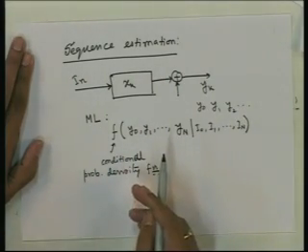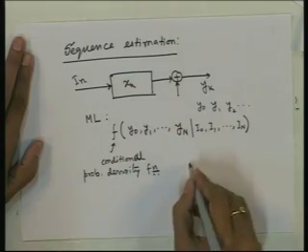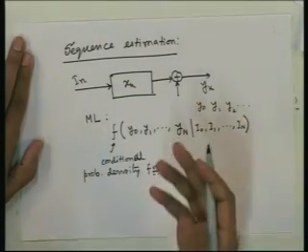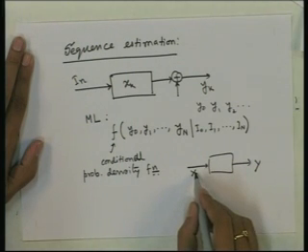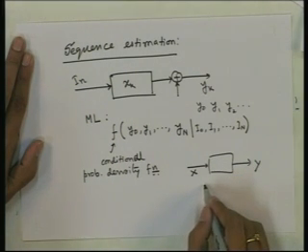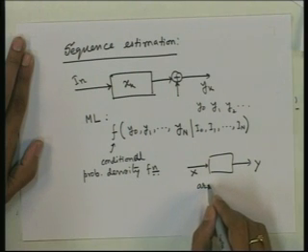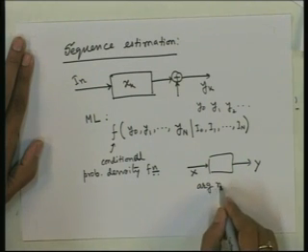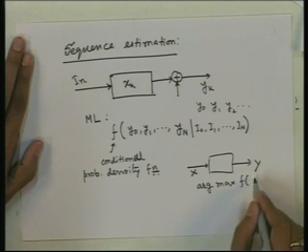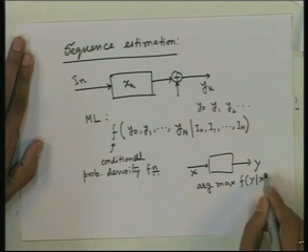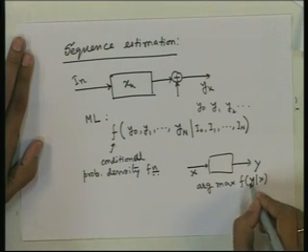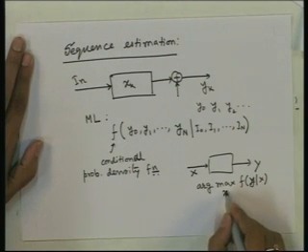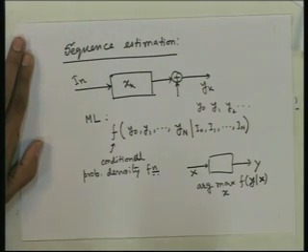That is the maximum likelihood estimation we know, because originally, in another context of detecting symbols, we said that we are transmitting one random variable x and we are receiving one random variable y. The maximum likelihood estimate of x is the value of x which maximizes f y given x, the density of y given x evaluated at the received value. So, we want to maximize this, that is the maximum likelihood estimate.